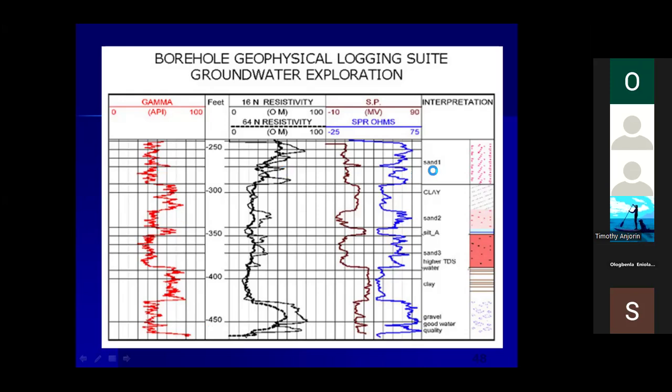You can see here, around 250 to 300, we have sand. Around 300 to 310, we have clay. Around 310 we have sand. Okay, and we have silt there. So you can see the particles being retrieved. Okay, this is the interpretation.